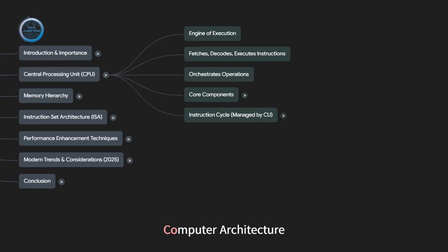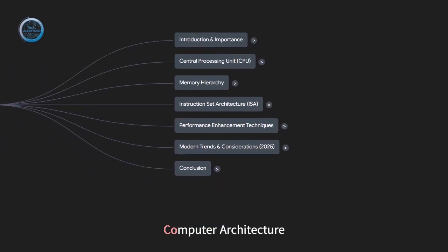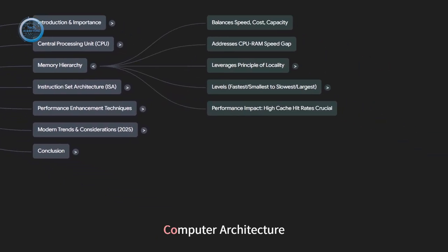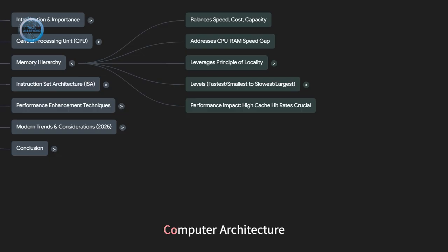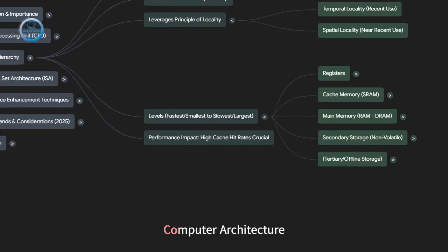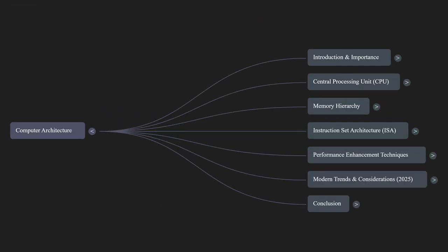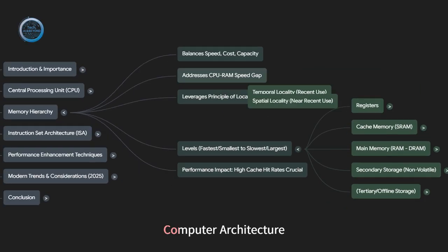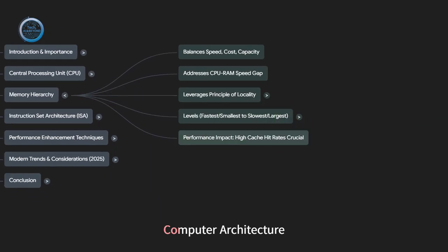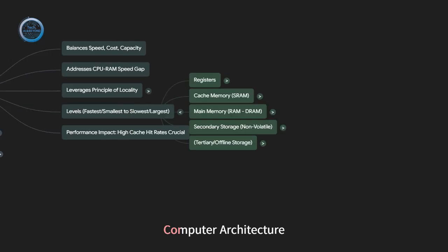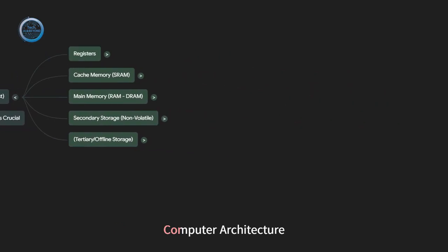And the third key piece. Yes. Registers. These are small but incredibly fast storage locations right on the CPU chip itself. Like tiny bits of memory. Tiny bits of very fast memory, much faster than anything else. They hold the data the ALU is actively working on right now, the instruction that's currently being processed, the address of the next instruction to fetch, that's the program counter or PC. The PC, right. And other temporary results or status flags. Their speed is critical. They give the CPU immediate access to the data it needs most urgently.